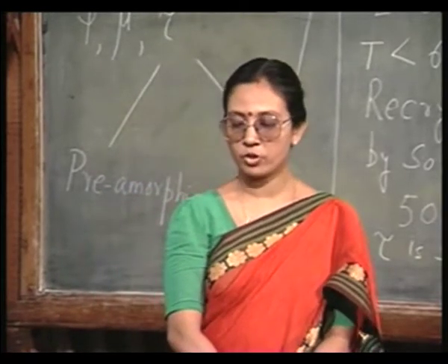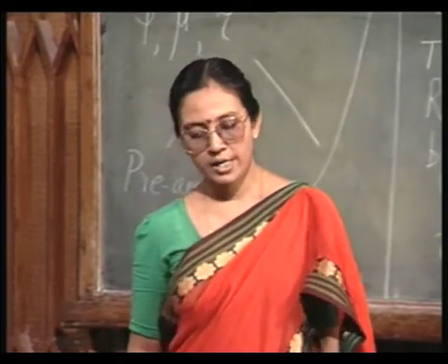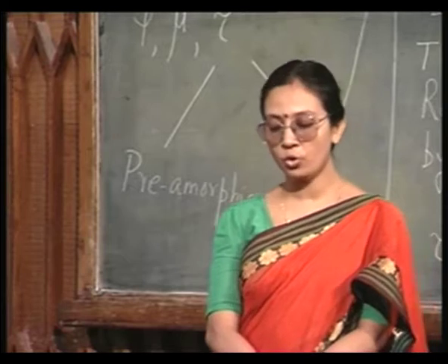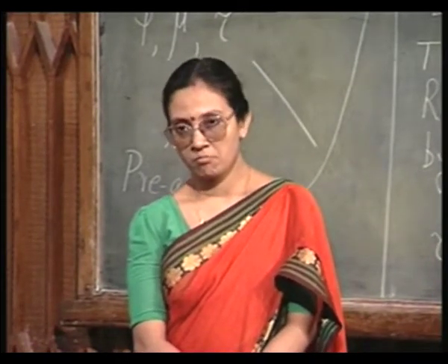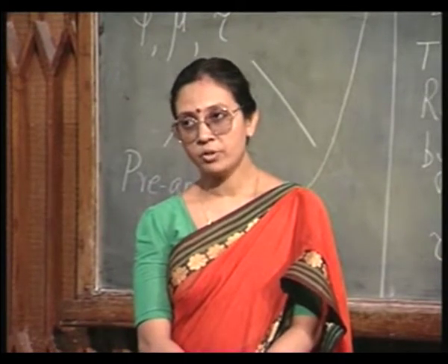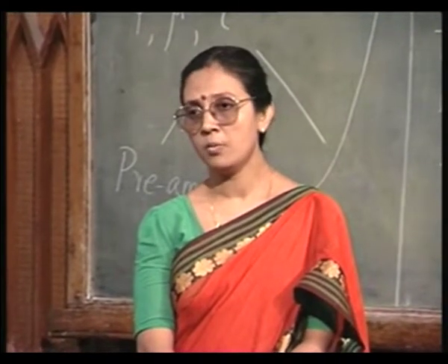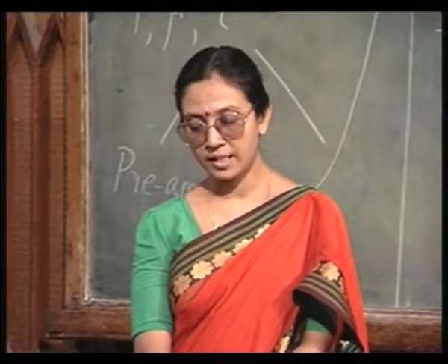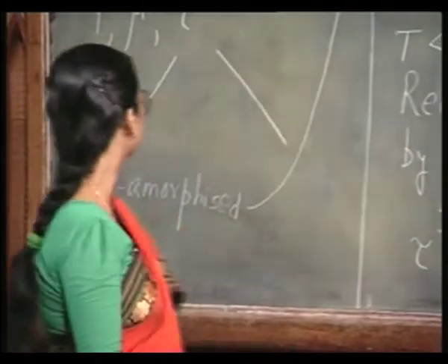In this case, of course, I have a low dose, light ion implantation, you have full recovery of all the parameters, conductivity, mobility as well as lifetime, by 800 to 950 degrees centigrade.